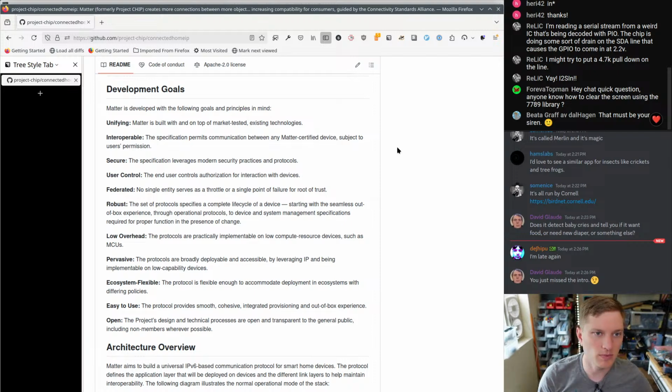So I fixed a number of bugs on the Espressif port this week. If you're using Espressif, try the absolute newest. There's a pretty bad BLE memory leak that I fixed this week. If you're using the C6 or any of the other C series or the H2 that uses their USB to serial converter, and you're using it with code.circuitpython.org, I have a fix in that makes it work better. Yeah, so I can go into those fixes as well, but